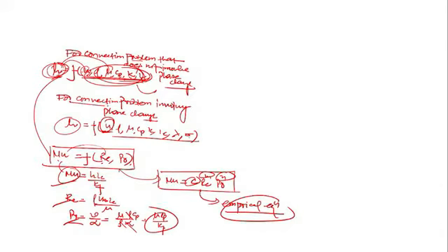When I consider the convection problem that involves phase change, then it is much more complex because two additional parameters will come into the picture. One is the size, and the size of the bubble is decided by surface tension, that you know, and lambda is the latent heat of condensation or evaporation of the phase change. So this is what is more complex. Clear? This is all about your convection. Is this clear about the convection, my dear student?